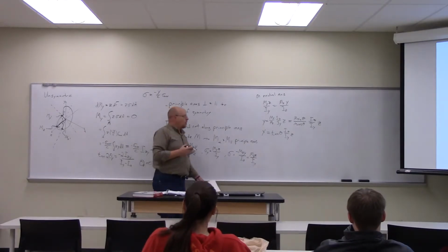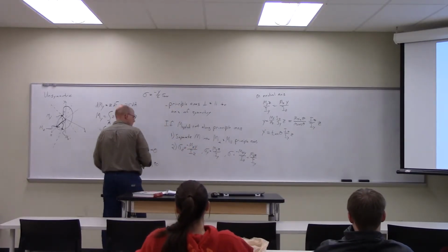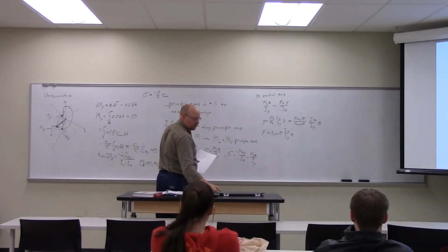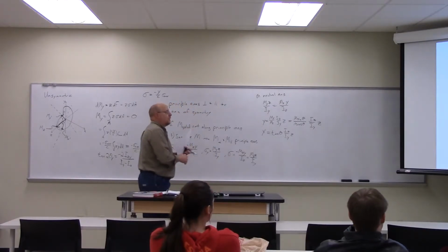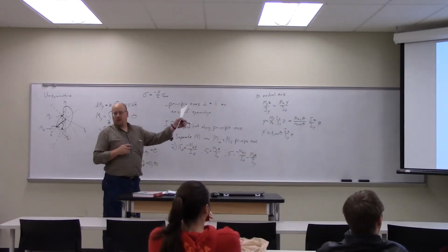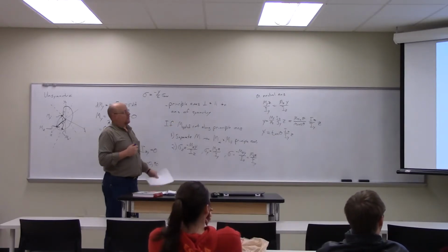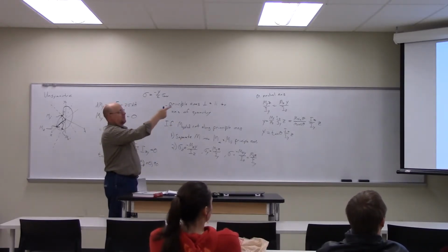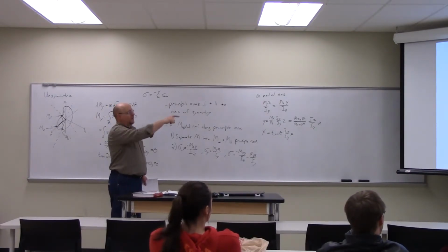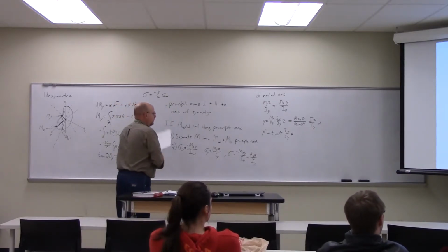So if I want to find the orientation of the neutral axis, I have better pictures down here. Yeah, there it is. You can kind of see there the better components on the second figure. See how you take that moment in the upper left corner, break it into components along the z and y axes, right? And then each of those gives rise to a stress distribution.